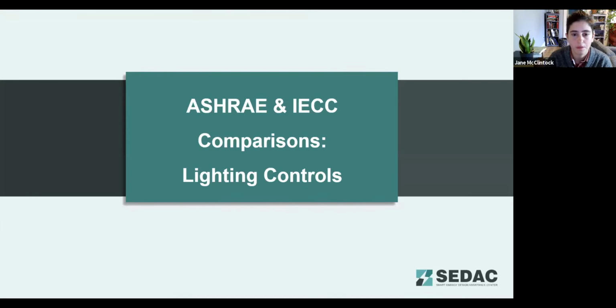And looks like we've got most of the answers in for the poll question here. Let's go ahead and share those. So in our sample meeting room, we did need occupant sensing controls because it was unpredictable use. Light reduction controls were not required for that. Manual controls, you do need manual controls even if you do have occupant sensing controls. So good pickup on that.